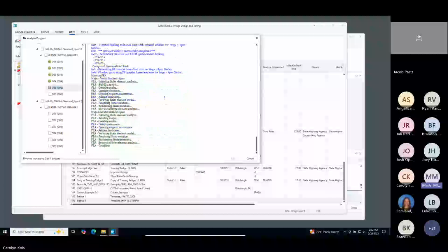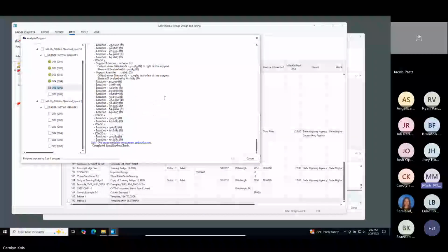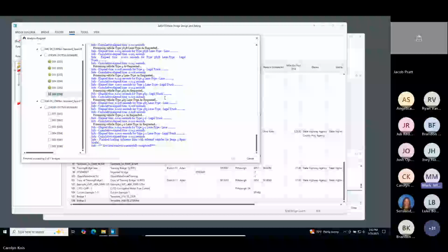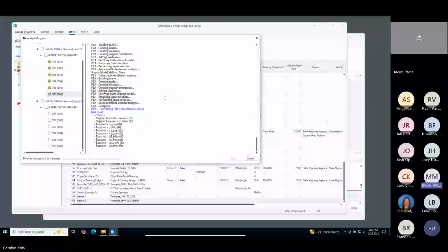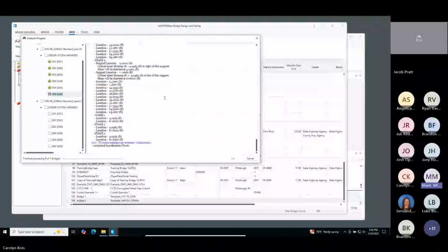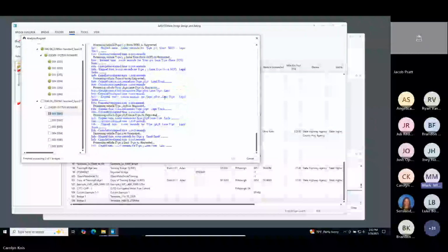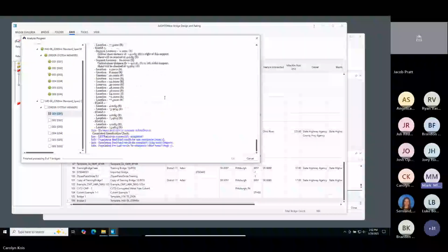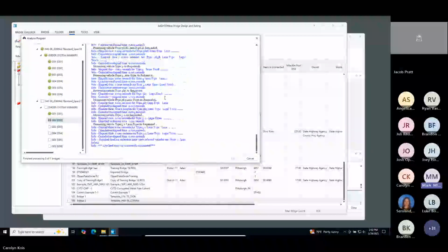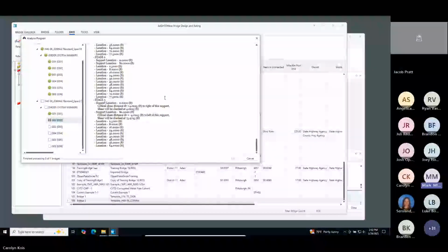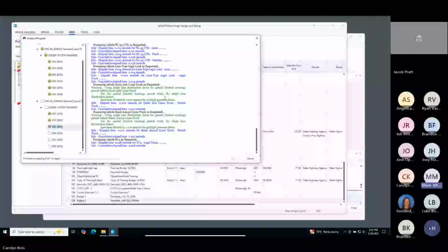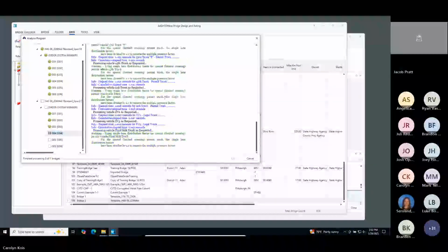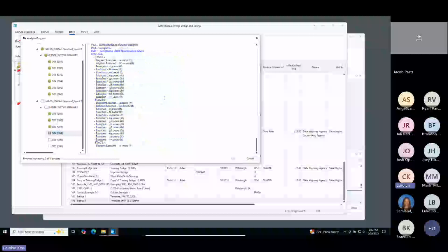And the nice thing about this is when you're in the bridge workspace, you may have multiple superstructure definitions, like a combination of steel and pre-stressed bridges that make up the entire bridge. When you run it from the Bridge Explorer, it's looking at all of those, and the results you're going to get are the controlling rating for the entire bridge. Yes, exactly.